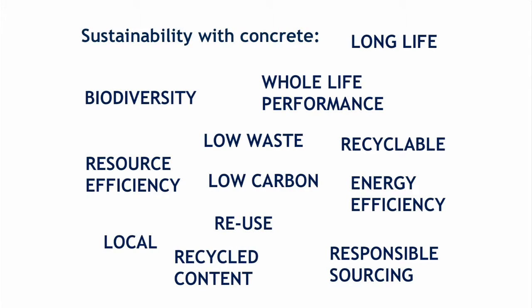There are many different aspects to think about sustainability: biodiversity, low waste, resource efficiency, and all of them are going to vary according to the type of building that you've got or what your client requirements are. I think carbon probably has risen to the fore as one of the key aspects. In terms of operational CO2, it certainly forms the backbone of BREEAM and Code for Sustainable Homes, and of course the other government initiatives for zero carbon homes and zero carbon buildings. They're all about operational CO2, so that's the carbon resulting from the energy use of a building.